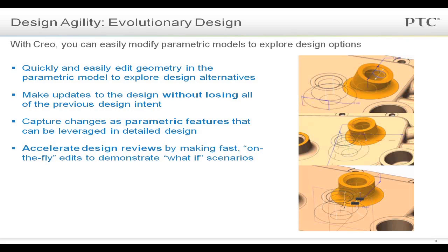I'm building new features. And because I'm building new features, all the capabilities which you see inside Creo Parametric, with the likes of family tables or user-defined features or interchange assemblies, all that good stuff, still works because I'm simply adding parametric features which are, for example, moves or warps, etc.